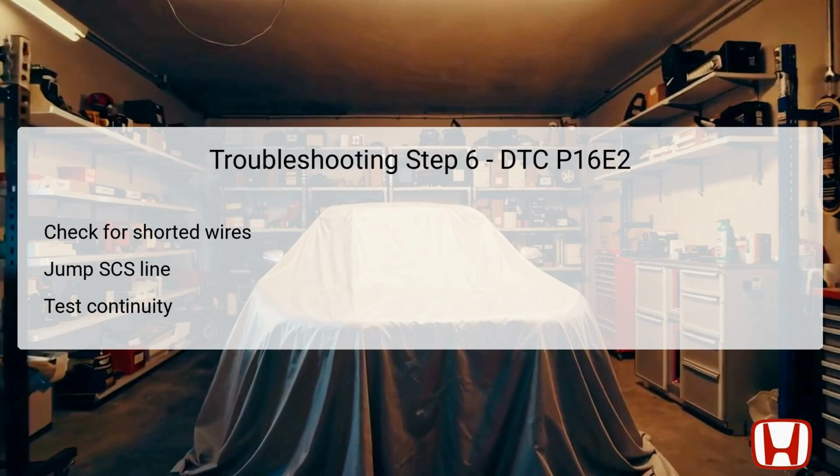After successfully jumping the SCS, the next action is to test for continuity between the alternator's 1P connector terminal and body ground. This test will involve progressively disconnecting each relevant connector one at a time, including the PCM connector A, 12-volt battery sensor 2P, and others as specified in the diagnostic instructions. If at least one disconnect results in discontinuity, it shows that the LIN wire is in good condition, while failure to find discontinuity suggests that shorts exist within the LIN circuit, requiring further repair.